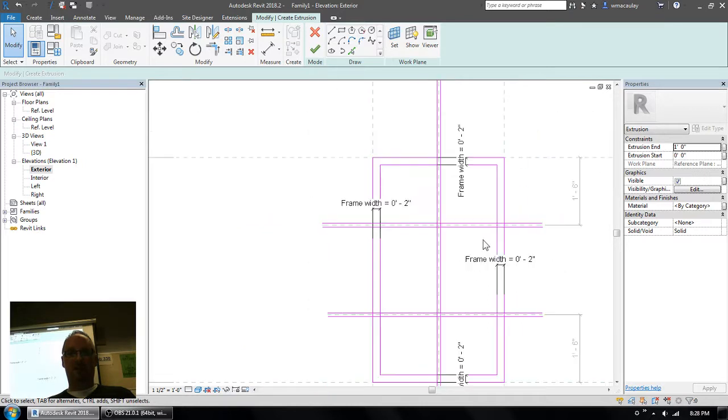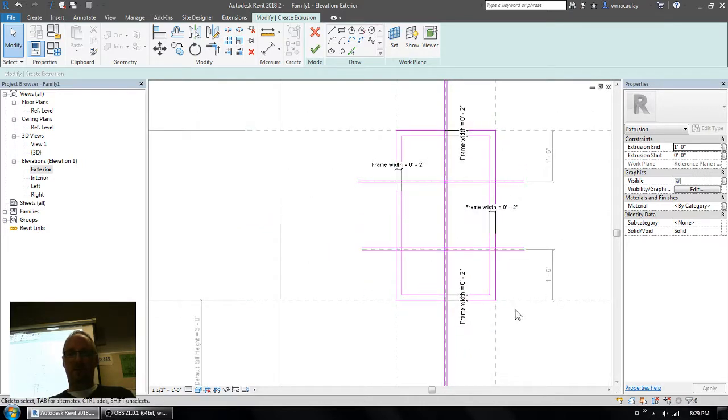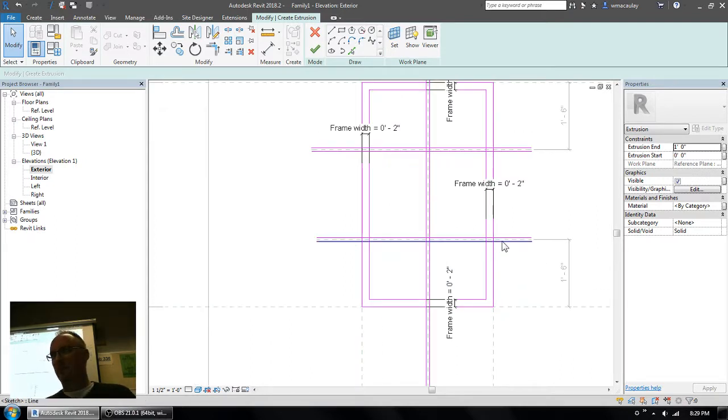Okay, so you should see all these pink lines on the outside. You've got these pink lines on the inside. So now I'm going to walk you through the process of cleaning this up. Now, on the outside here, our outside edge is fine. That's not the problem. But to make a valid floor sketch or a valid roof sketch in Revit, you can't have any intersections and you can't have any gaps. So here is the quick way to do this as painlessly as possible.